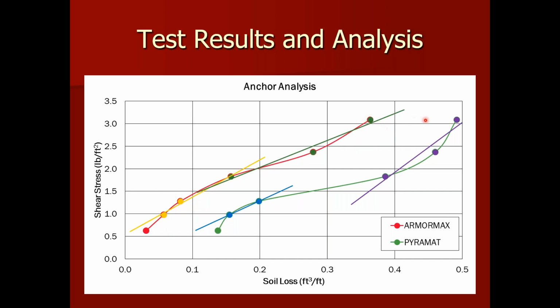And then you get some soil movement and then it begins to flatten out. So that process of the sine curve essentially associated with soil loss is directly related to the bed form functions that we know exist. But functionally for design, we want to understand sort of the bins that we're in for shear stress and how can we best pick a product knowing what that initial event might be before our vegetation gets established.